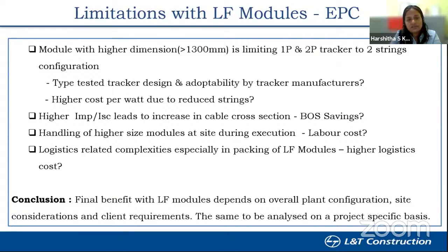Finally, all these aspects need to be studied when we are looking at an LCOE point of view. So the final benefit with the large format modules depends on the overall plant configuration. It also depends on the site considerations, as well as the client requirements, client specifications, as well as client eligibility criteria. So all this needs to be taken into consideration when we are concluding the benefit of a particular LF module over another, or a particular LF module over the earlier type format modules, to arrive at the final selection. And this has to be analyzed on a project specific basis.